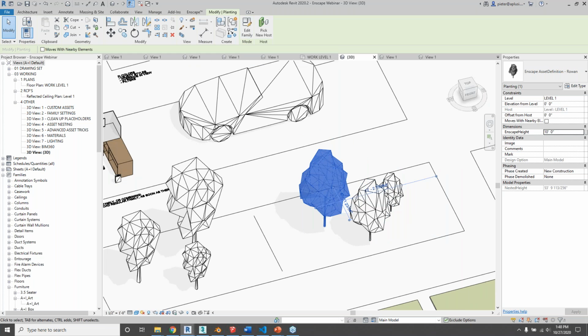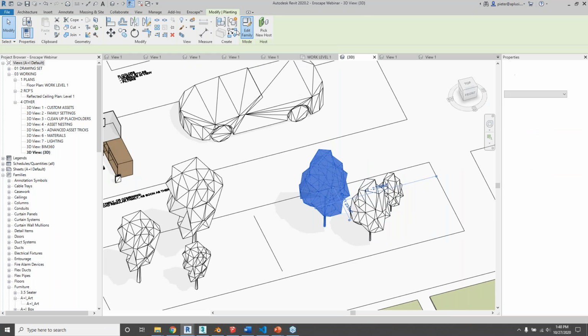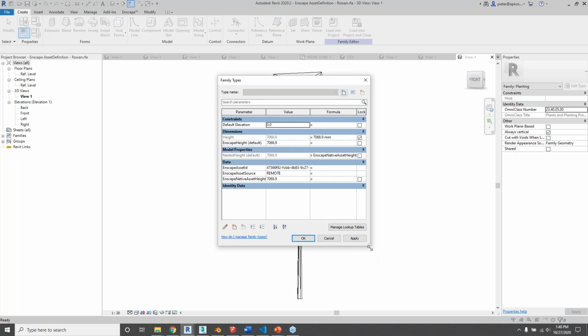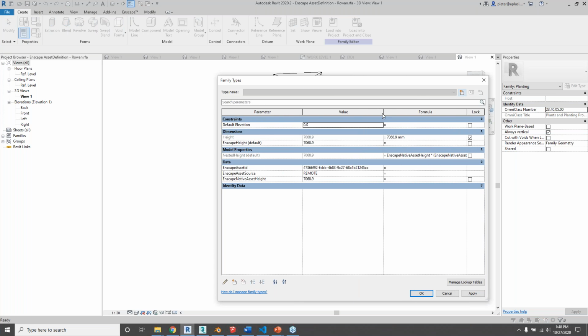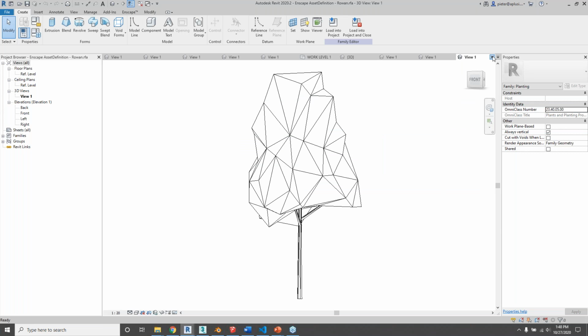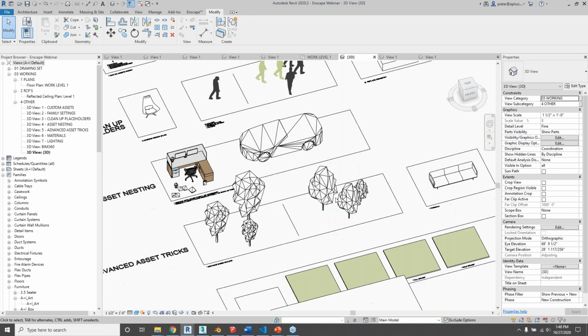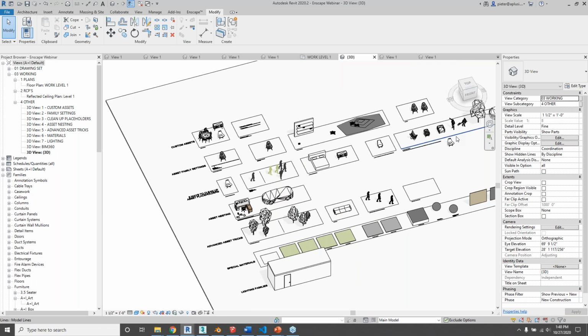So just go to this family, edit family, and check out the parameters set up here. So you'll need both this formula, this parameter, and then lock the height with a formula. And then it will just work. This workaround unfortunately does not combine with the hidden edges. For some reason, it doesn't work.